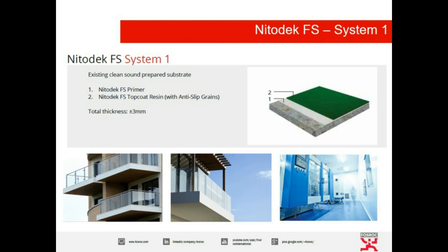So that's Nitodec FS System 1, primer and then 2 top coats. The two top coats allow you to actually put down a broadcast of aggregate between the top coats. So that gives you a bit of slip resistance on that side of things.